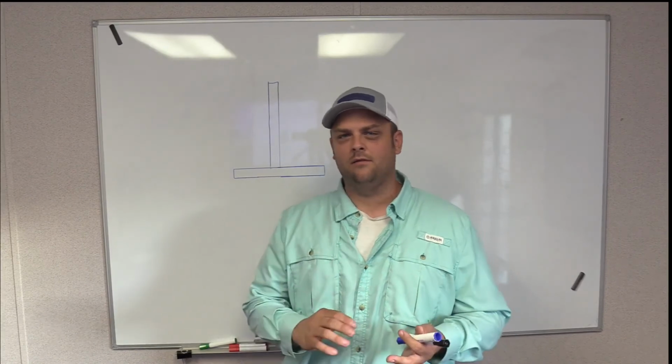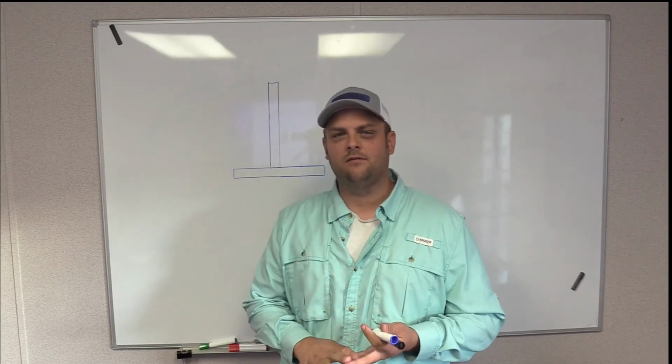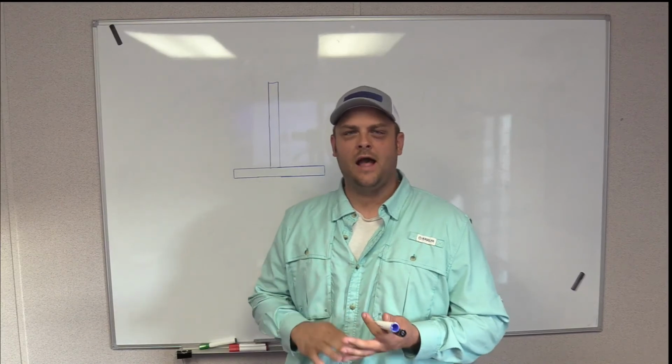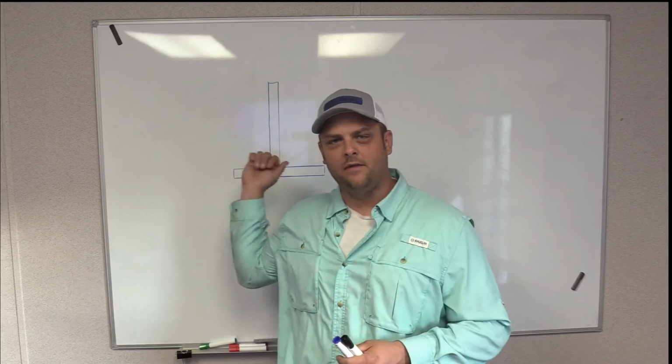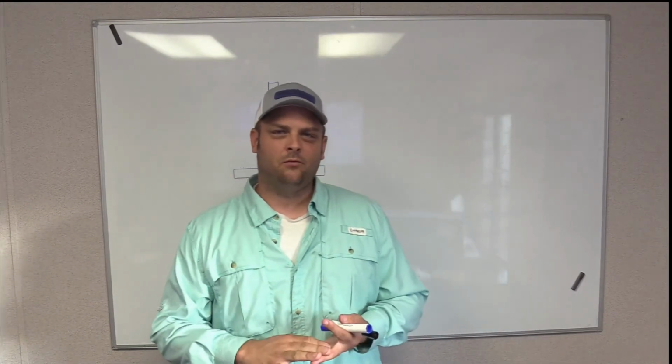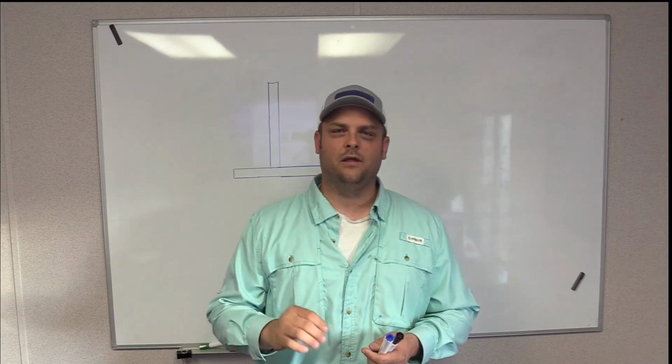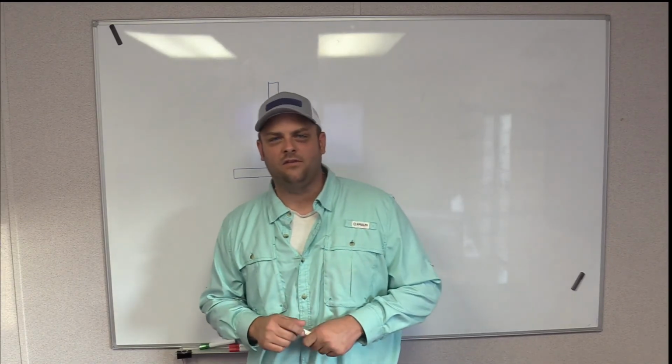The first one is the 3 characteristics of a weld throat: your actual throat, the effective throat, and the theoretical throat. And I'll be drawing that on the board here in a second. The second one is that they want you to calculate the weight of a piece of steel.